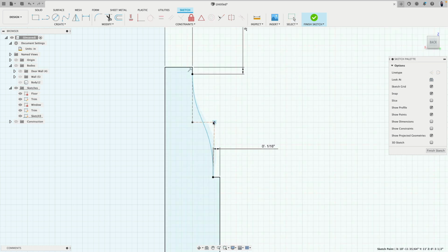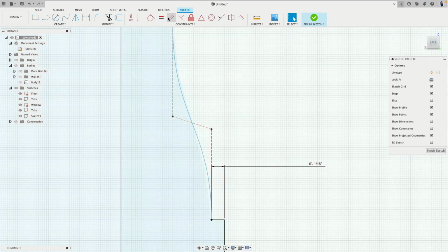Here I could do the same if I want to. And it's actually also nice to see how, for example, this bellies out a little bit. Can play with this a tick more. This is a 1/2 inch. Maybe these two lines I make equal first. Ooh, okay, hold on. Let's do it this way. We make these both vertically constrained. Then we make this and this equal. Thank you. And then we make this horizontally constrained.